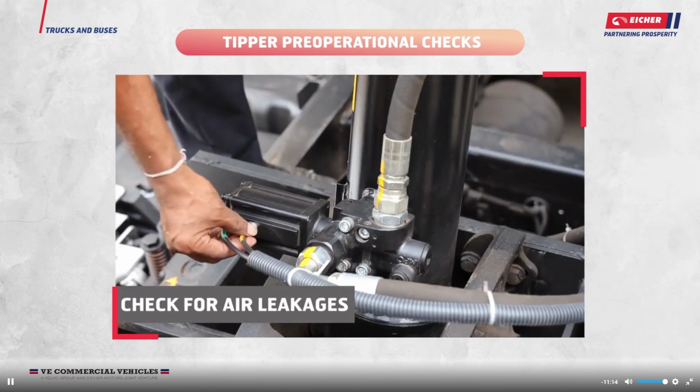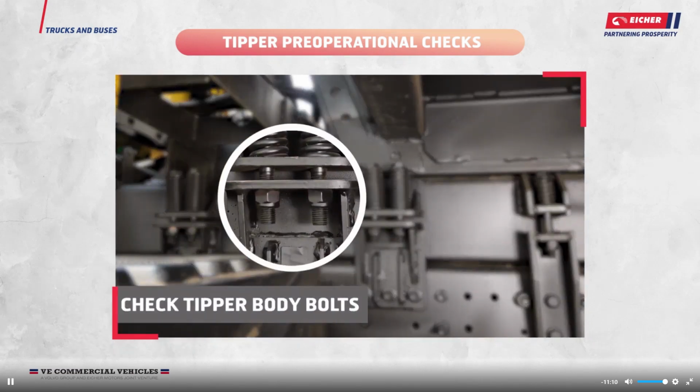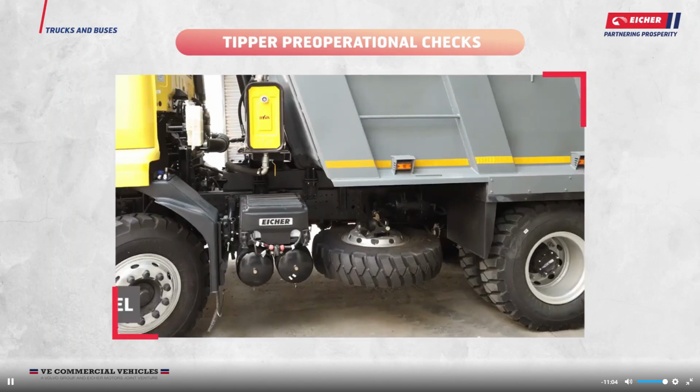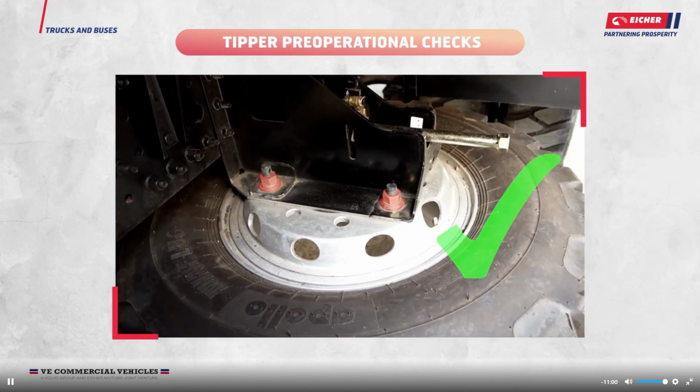Check tipping system control valve and pipes for air leakages. Check tipper body mounting bolts. If found loose, get it tightened immediately. Check the spare wheel condition and its proper mounting.